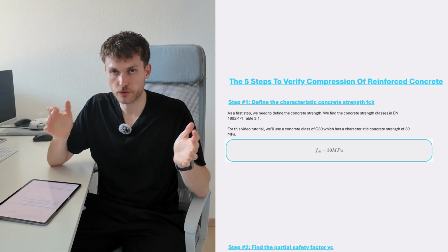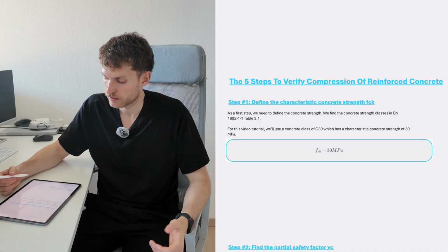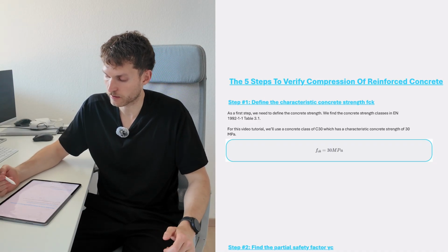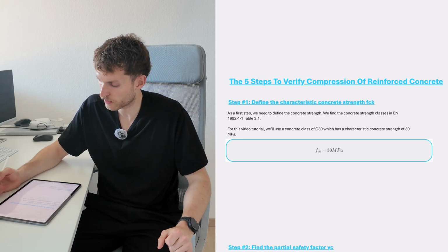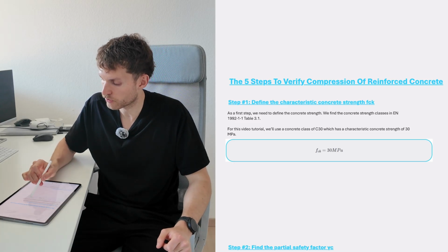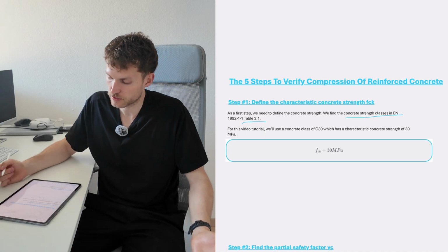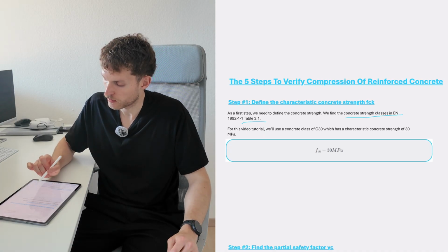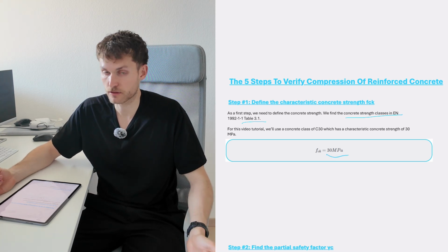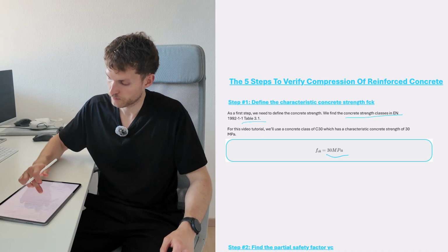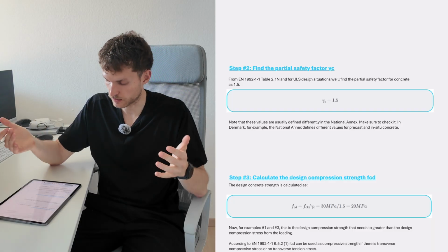Alright, now let's run through the 5 steps to verify compression of reinforced concrete. Step 1, define the characteristic concrete strength, FCK. As a first step, we need to define the concrete strength, and we find the concrete strength classes in Eurocode table 3.1. And for this video tutorial, we'll use a concrete class of C30, which has a compression strength of 30 megapascal.